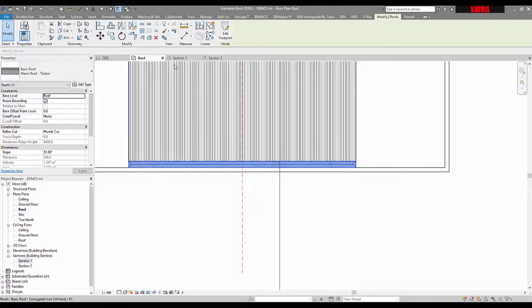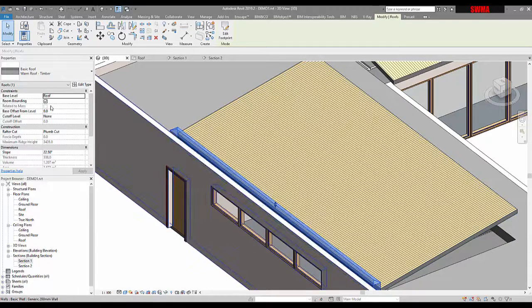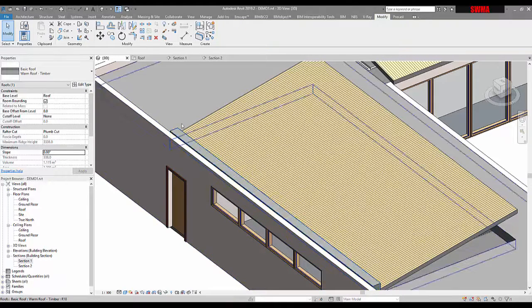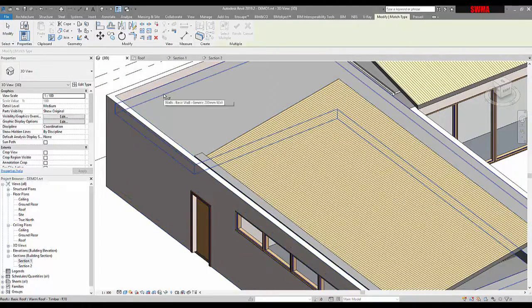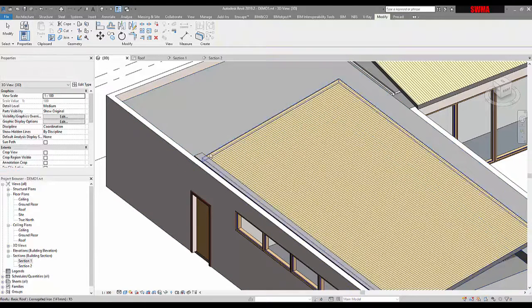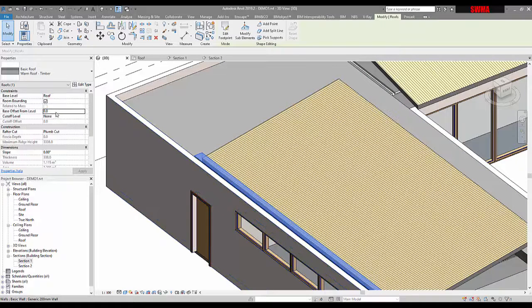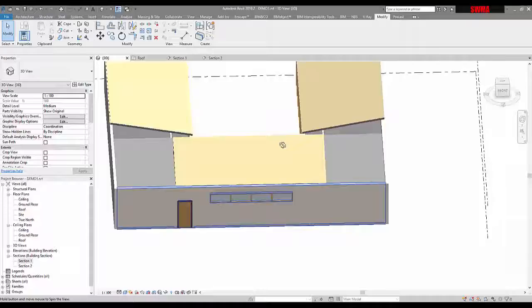Now you can see it's got a little default pitched roof there. I don't want it to be pitched. So I can actually just go and hit no slope. That was going to be a flat roof, and like the other ones, you can see this one is sitting at -338. I can go and hit the MA for the properties. So let's just bring up this one, MA. Bring that one down. Is that going to bring it down? No, it's not. Okay, I'll just go here and go -338, and that will drop it down to give us a little parapet, which we can detail up later.